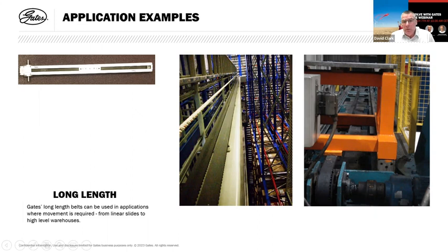You can see the belt drive there and up through the middle that is moving a platform or a positioning system horizontally back and forward. So belt drives can be used in many cases like this. Again, low maintenance and zero lubrication. And there's a wide range of belts for many different applications, from 14mm pitch down to 3 or 5mm pitch on the smaller versions.